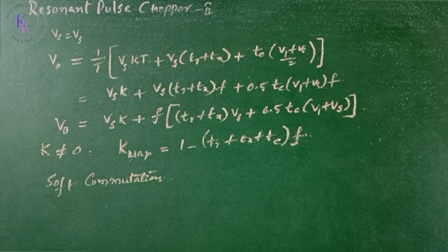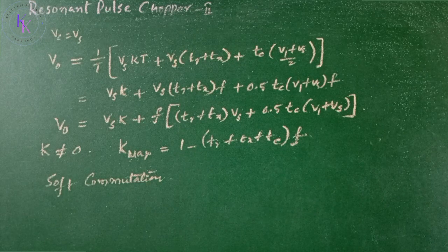The resonant reversal is independent of thyristor T1. However, the inductance Lm overcharges the capacitor C, and this will increase the voltage rating of the components. After T1 is fired, the capacitor has to reverse its charge before turning off the thyristor T1. This is an inherent delay in the commutation, and this limits the minimum turn-on time of the chopper. And the commutation time Tc is going to depend on the load current Im.